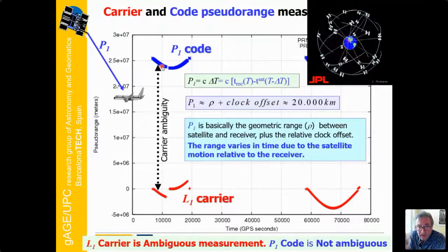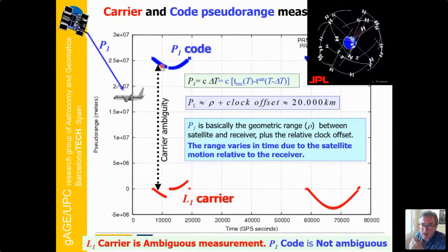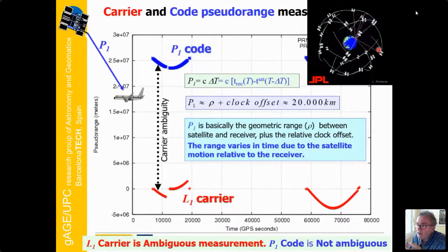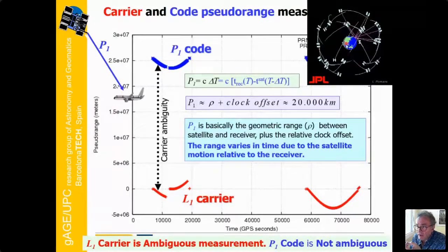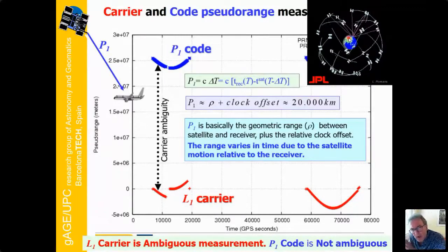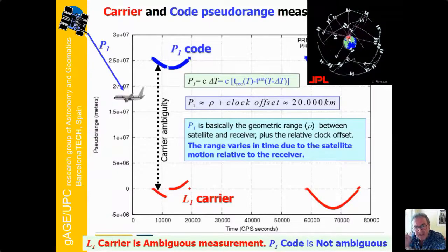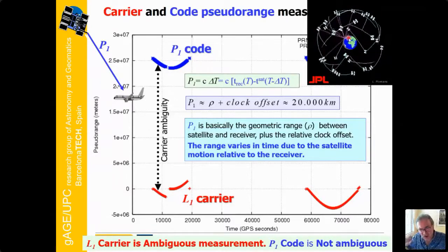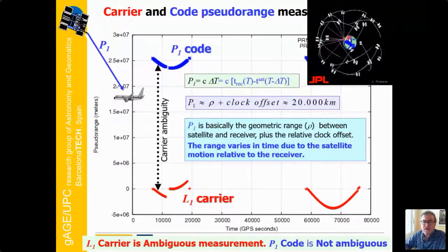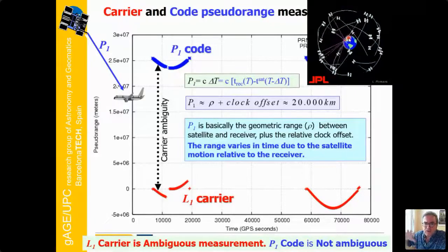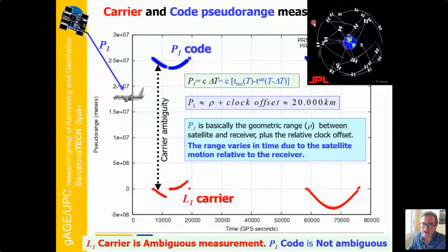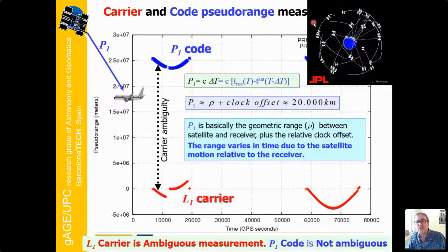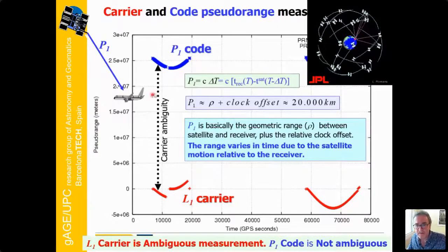The value that the measurement gives, estimated from the traveling time from satellite to receiver, is an estimation of the apparent distance from satellite to receiver. What does it mean, apparent? Well, apparent because these measurements, as I commented, are contaminated by different error sources: clock synchronism errors, atmospheric propagation errors, and so on. This is why I say pseudorange or apparent measurements.